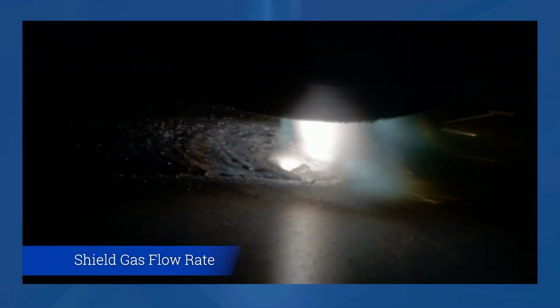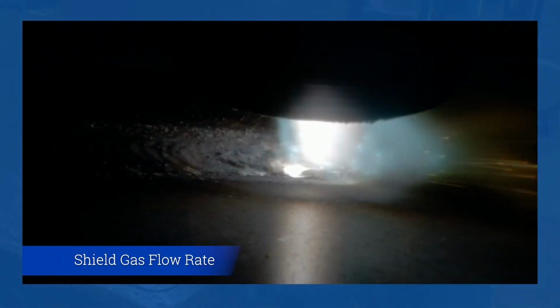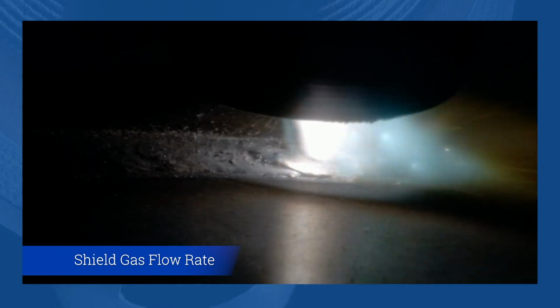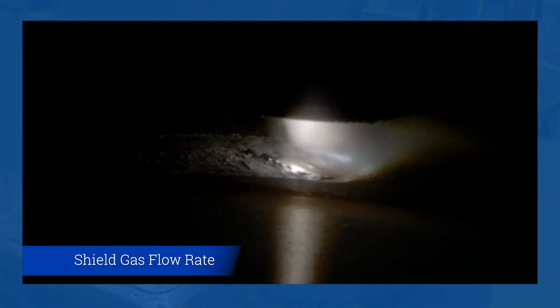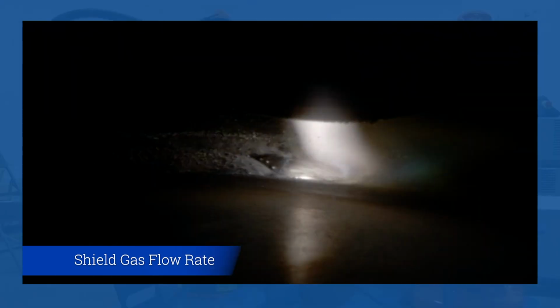Let's talk about shielding gas. This is one of the easier variables to set. Typically, you just follow the manufacturer's directions on the torch. Here we have it set properly. Now we're turning it up too high. What you see is the gas is actually distorting the arc. We're blowing the arc around.